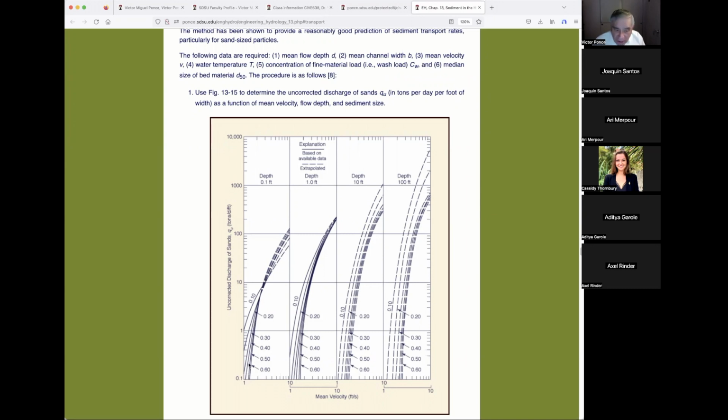So we have ripples, dunes, plain bed over here already, because it is in accordance with the bed configuration, from which we conclude, after a whole lot of research and observation, that what is actually happening in the real world is that the bed forms are making sure that the transport is reduced. Because by the time you get to the higher transport, there are no bed forms and you can transport a whole lot. How is that? The idea is that the bed forms are impeding the transport. They are reducing the amount of transport.